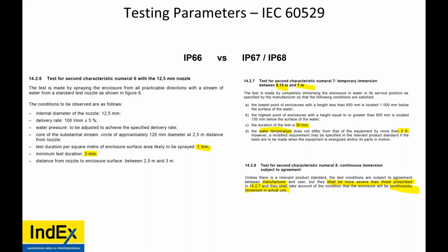But to give you an idea, humidity, which is the gaseous, vaporous form of water, hot air rises. If you have a breather drain at the bottom of the device, it's really only operating as a drain. It is a very poor breather, because that humidity is going to stay trapped inside and rise to the top of the box. And when the box cools down, that is going to condense into water.